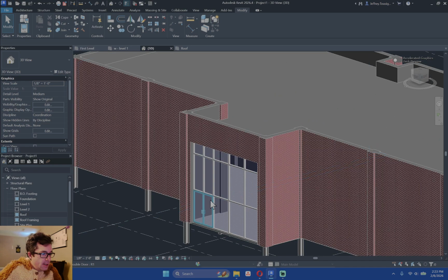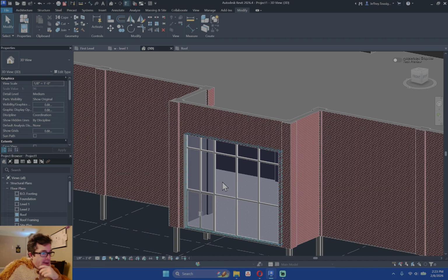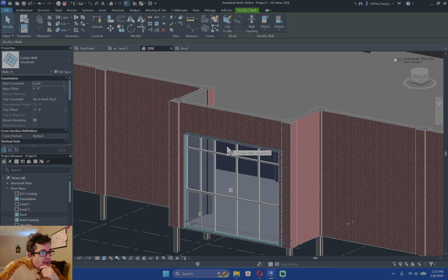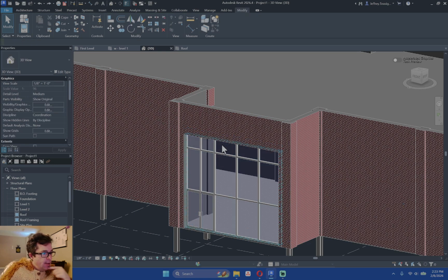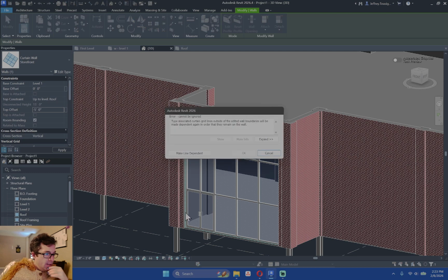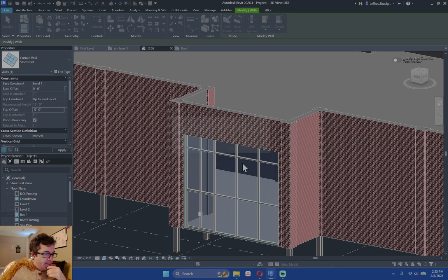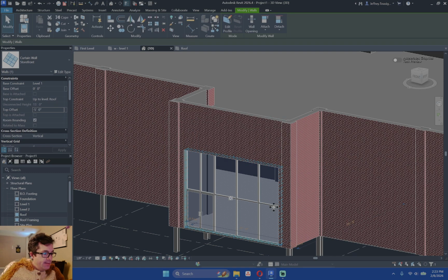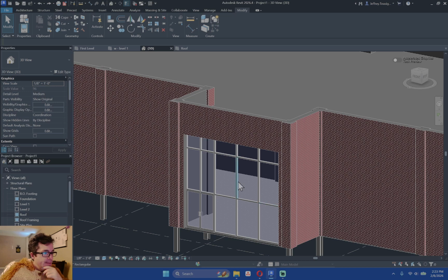Okay. So we have a couple options. The curtain wall can go up a little more. That'll give us more window at the top or bottom. We can lower the curtain wall so that we just don't even have to worry about an upper clerestory.